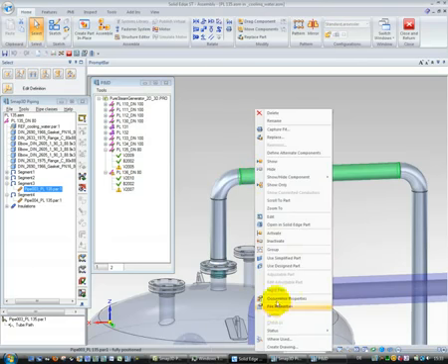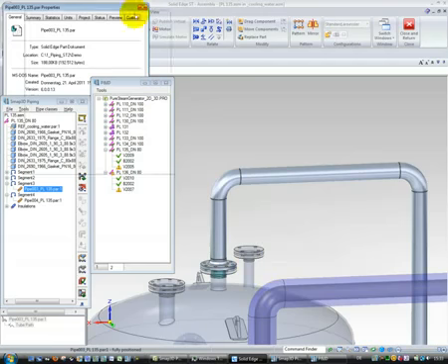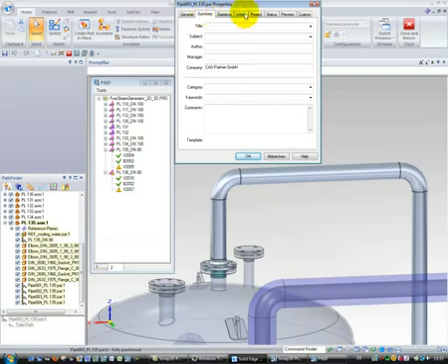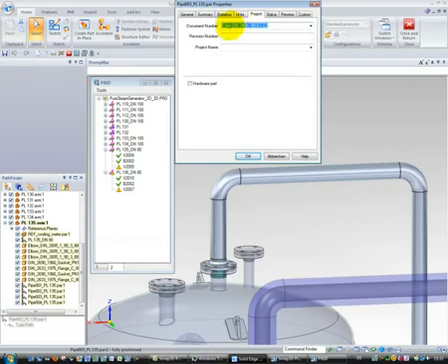So here we can take a look into the file properties of such a component, and we will see that the software writes and knows, for example, the standard from which this pipe is used, the geometry, the diameter of the pipe and the wall thickness. This information we automatically write into the component when we create the pipeline during the generation process.